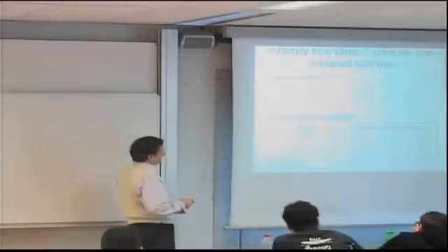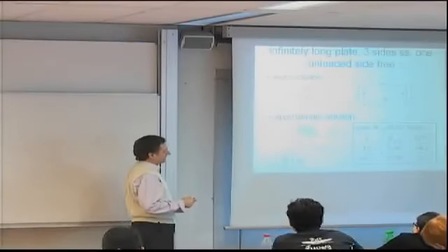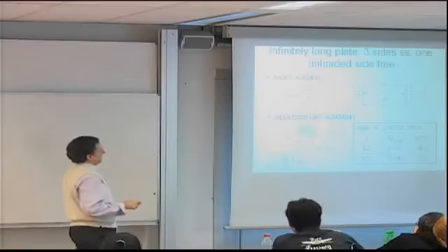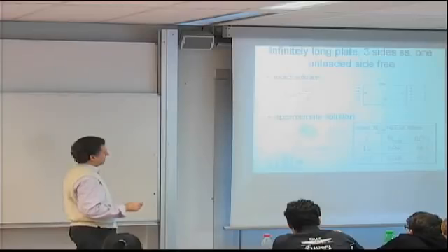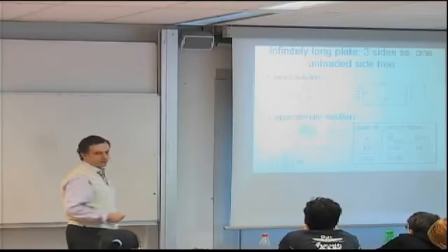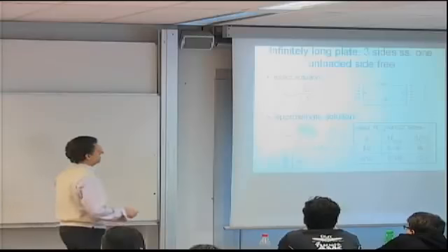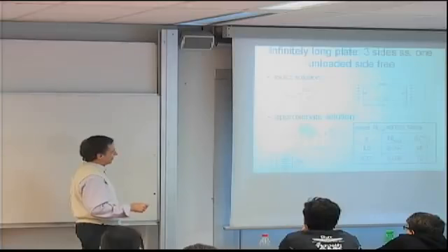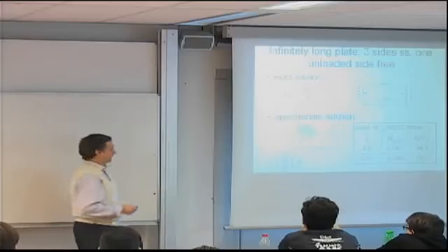Our approximate solution for an infinitely long plate, if we just take the expression for n0 from the previous chart, looks like this. And now you can see I have the d66 over b squared term, but depending on the lambda that I can use, 1/2, 5/12, you can pick other values obviously. Depending on the value of lambda, this coefficient, 4 pi squared lambda squared, will be 6.9 or 9.9, which of course is not 12. It's actually significantly less than 12.